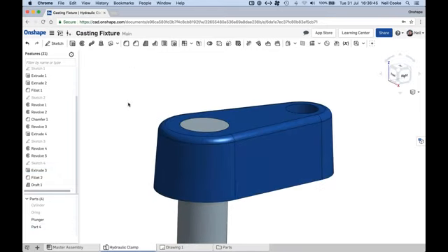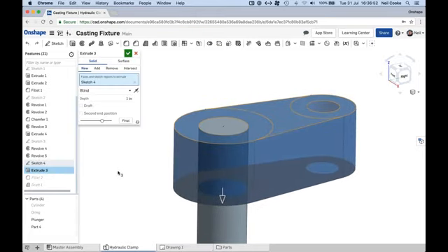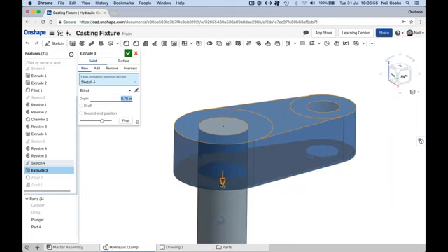Okay, so that's the basic shape. One other nice feature I think it's worth showing, if you wanted to modify perhaps the size of this thing, you do have the view manipulator in there, so you can modify it. But of course, editing an older feature means that any of the future features are suppressed while you're editing it, so you can't see what the effect of that is.